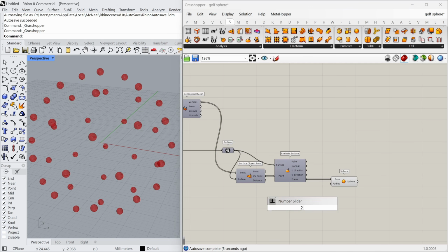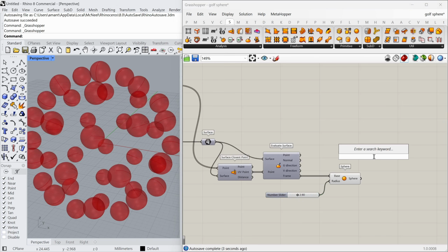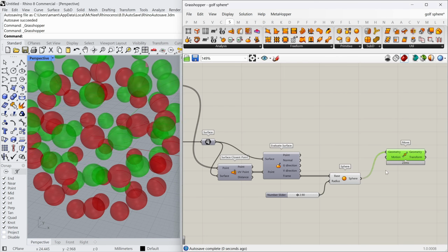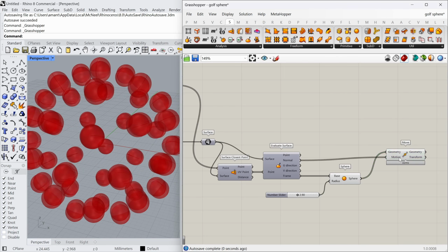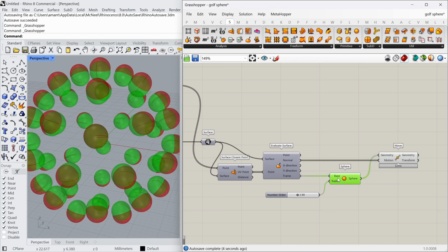On each normal plane, create a small sphere with a radius of around 5.8 millimeters. Then move these spheres slightly in the normal direction, outwards towards the golf ball. This creates that concave dimple shape.